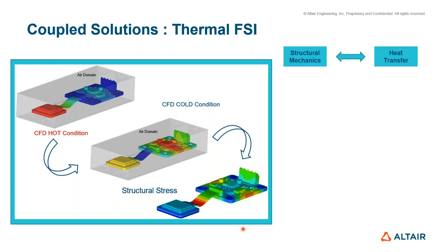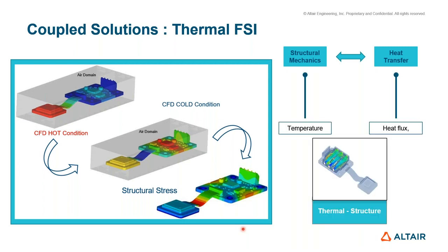Now, the TFSI is an integration between structural mechanics and heat transfer applications. This is enabled whether it's a unidirectional or bidirectional problem, depending upon the kind of problem you're solving. And there is a code coupling interface, which automatically takes care of mapping field entities, as you see, heat flux and temperature and so on. User-defined field mapping is also enabled in the SimLab environment, where you can decide how you want to do it. So you have the most automatic way and also a user-defined set pattern for yourself.